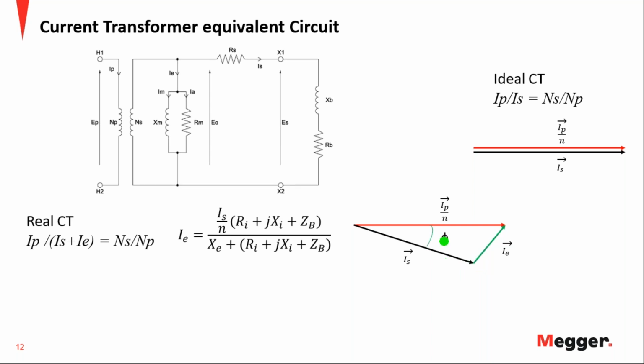And then for the phase deviation, we know that the limit is between 0.6 and 1 power factor, that is the corresponding cosine of this angle. So in this case you may have a deviation that is lagging more or lagging less, because we are always on the lagging side, at least for this case. So that defines your four limits.